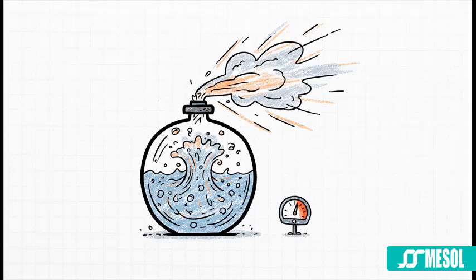Let's just take an emergency depressurization as an example. A steady-state model tells you nothing about the critical moments, like the liquid level swelling up inside a vessel, or the rapid flashing of liquid into vapor that could totally overwhelm your relief system. A dynamic model lets you see that whole event second by second. That data isn't just nice to have, it is absolutely vital for designing a safe system and for correctly calculating things like latent heat when you're sizing a safety valve.